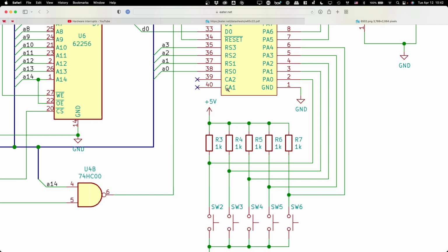We've got some 7400 series ICs. There's piles of them. They make a lot more than we do have, obviously, but what do we have? 2 input, single output, and there's 4 of those on each chip. So if I have 5 buttons, what are we going to have to do? We're going to have to do button 1 and button 2, and almost like a March Madness bracket, and button 5 gets a bye.